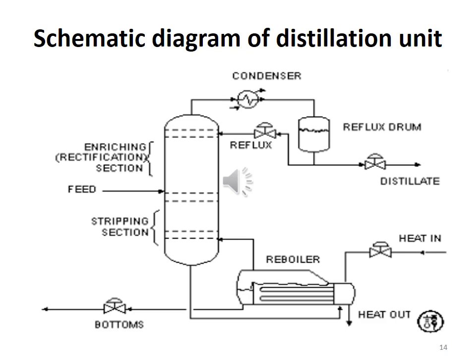The distillate section is where you can collect distillate into another container, while the remaining part is again sent for the reflux, and it is introduced in the distillation column for further processing. And you can see here the heat in and heat out. This is basically you can use a hot plate, you can use any instrument that can provide a sufficient amount of heat to the mixture components. So these components will go into the vapor state according to their volatility and the boiling point.